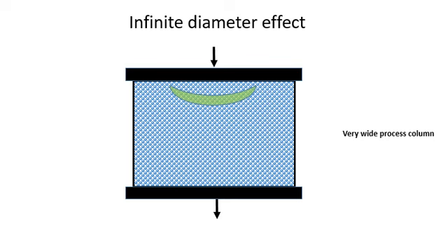So when it comes to process columns, there are several additional factors that would need to be considered while measuring dispersion. Maybe we could use a totally different approach to the one discussed in this presentation. Step change experiments with tracer solutions would give more meaningful information on the dispersion in very wide columns. Also, computational fluid dynamics, or CFD, would perhaps shed some light on the goings-on.